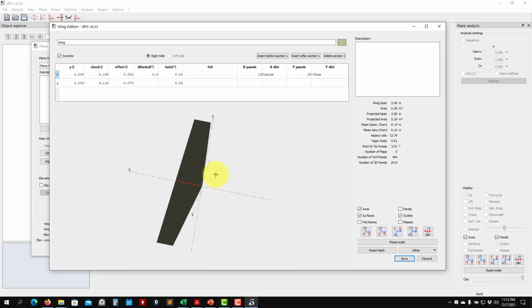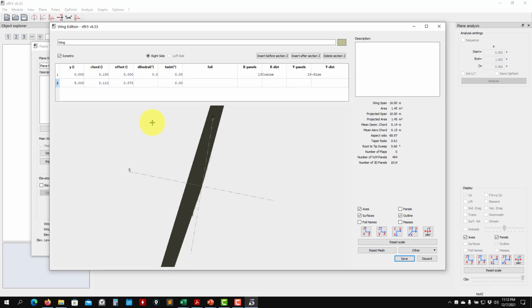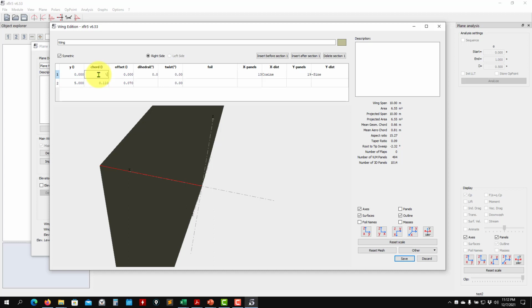And here you can design your standard wing. I will put any values here. I recall the rectangular wing was 4.6, the one in the example, so I will put here 5. Then the chord, let me put 1.2 here, and let me put 0.8 here. When you design, always check that this is giving you all the quantities. See that we have a taper ratio of 0.67. Let me reduce that to 0.4. Okay, too low.